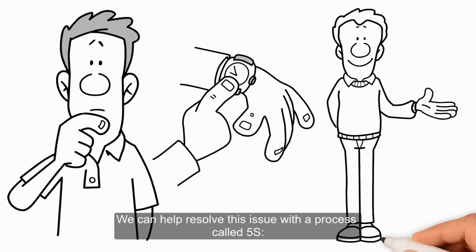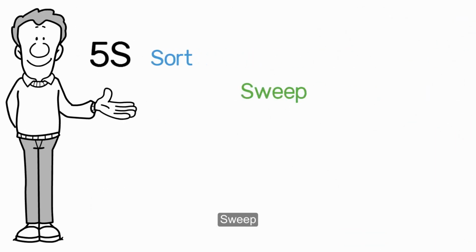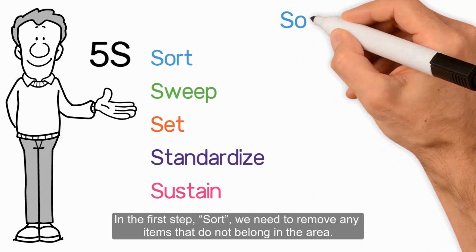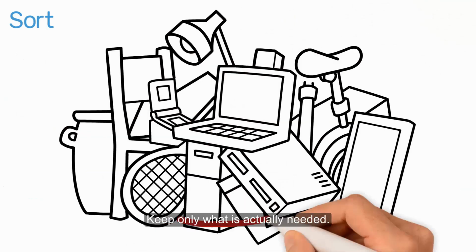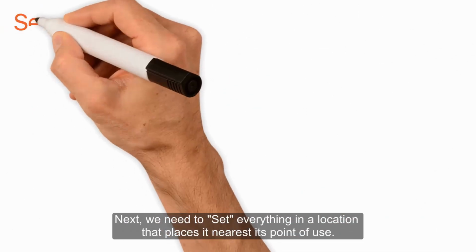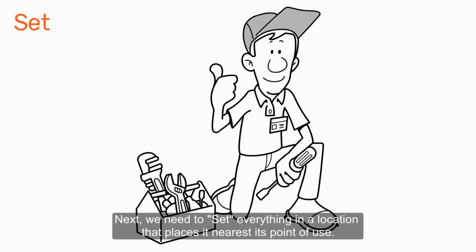We can help resolve this issue with a process called 5S. Sort, sweep, set, standardize, sustain. In the first step, sort, we need to remove any items that do not belong in the area. Keep only what's actually needed. Sweep consists of thoroughly cleaning the area. Next, we need to set everything in a location that places it nearest its point of use.